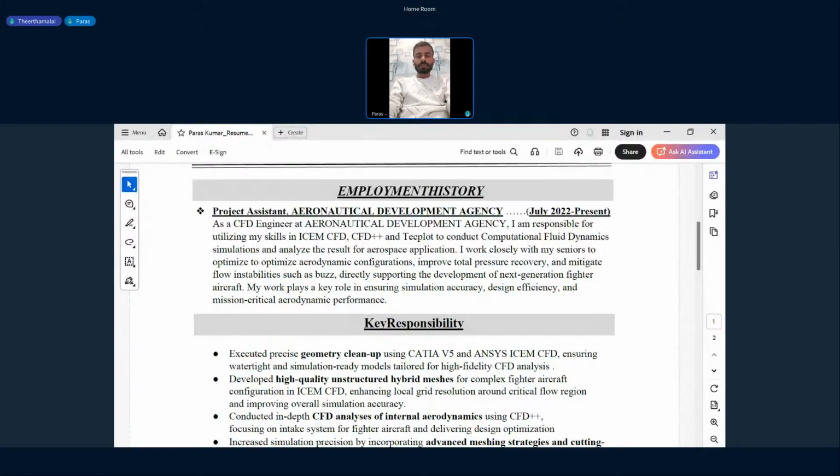If the combustion chamber pressure compared to the outside pressure is very high, the convergent nozzle will not be able to bring the pressure down to atmospheric pressure. There we have to use a convergent divergent nozzle. If the pressure ratio is high, we use a convergent divergent nozzle. When the pressure ratio is low, a convergent nozzle will be sufficient.